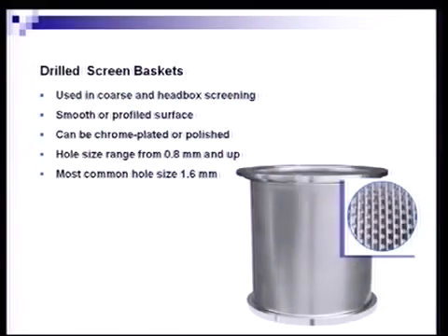This is the heart and soul of any pressure screen, the screen basket. This screen basket is the partner to the rotor, and between these two components is what really performs the duty of the screen, which is to remove debris that is large in two dimensions.